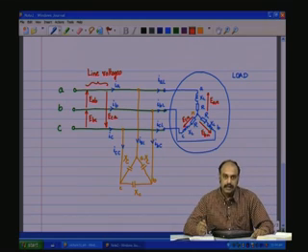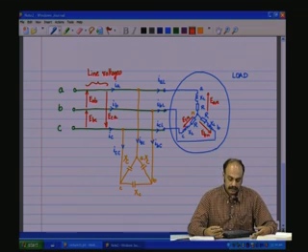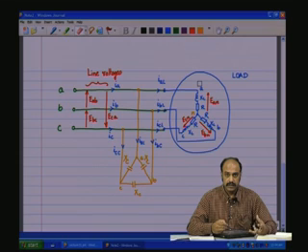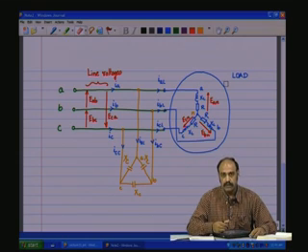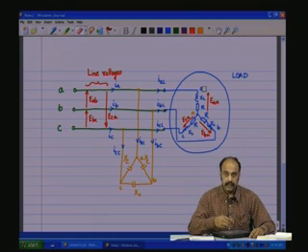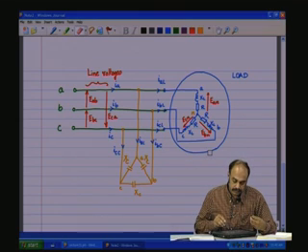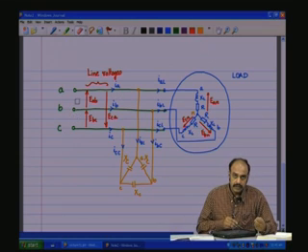So, this is the schematic of a very general 3-phase circuit system, where the actual load that we are seeing here is inductive in nature, as industrial loads generally are, because most of them drive motors, which are basically lagging power factor loads. If the power to be delivered to the load is very high, then the reactive component taken from the generator can be prohibitively high.